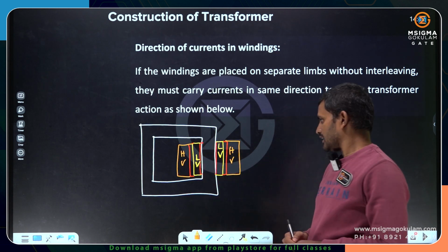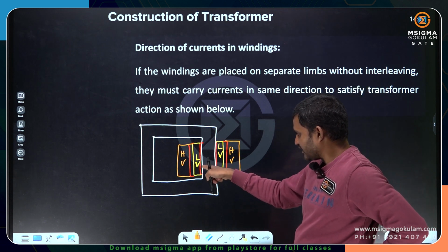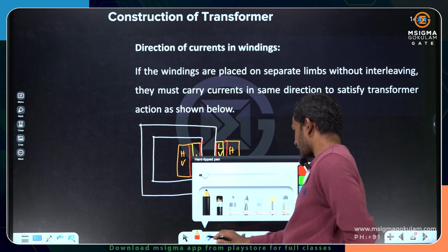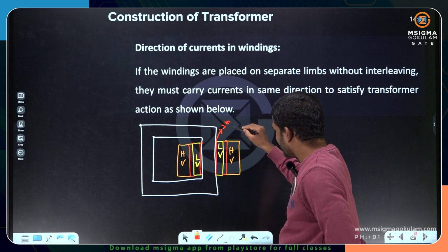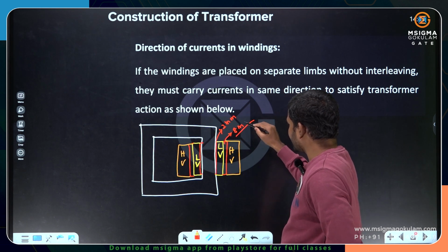Okay, right. So what I am trying to say is, because of placing the low voltage winding near to the core, the thickness of insulation is how much here? Maybe 2 mm and then 8 mm. So altogether it will be 10 mm.